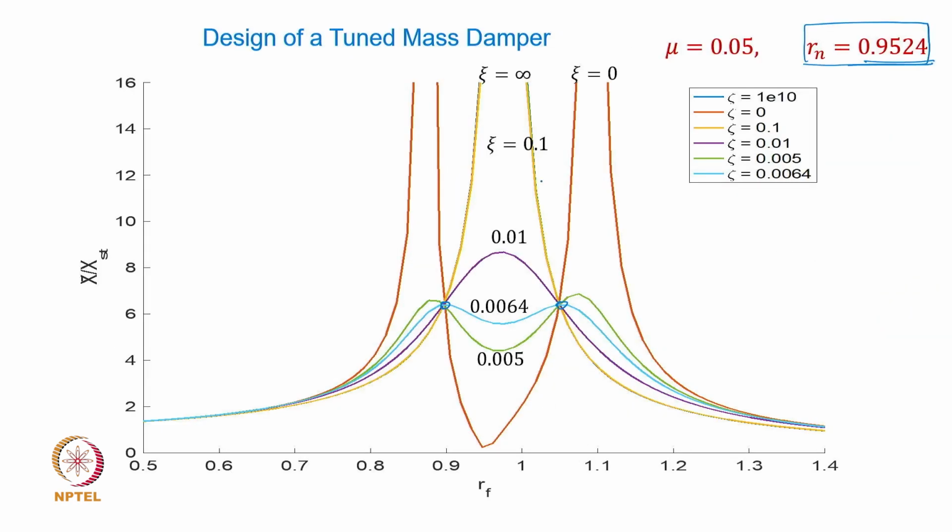So of all the various damping factor graphs that you see here, they do pass through this point, but they show up with a larger amplitude here or larger amplitude here. But this graph, if you look, focus on that graph, has an optimized damping factor which generates a zero slope at these two points, and then irrespective of where you operate throughout this frequency range, you do not get to see a large amplitude rise.